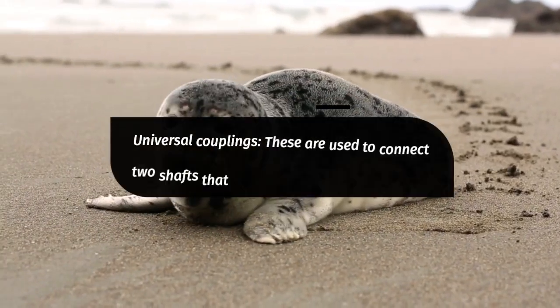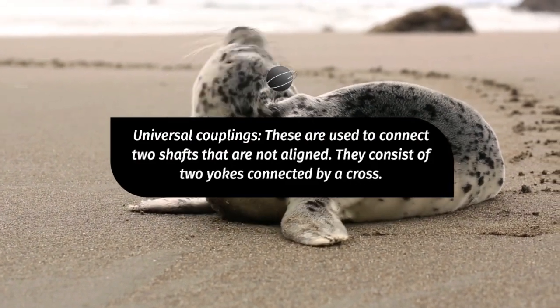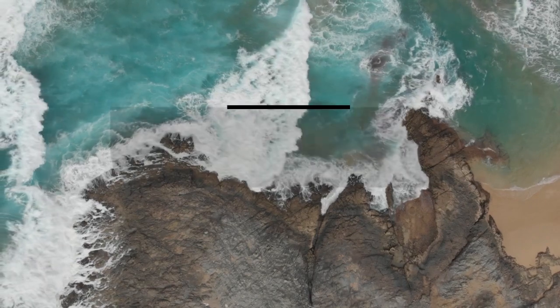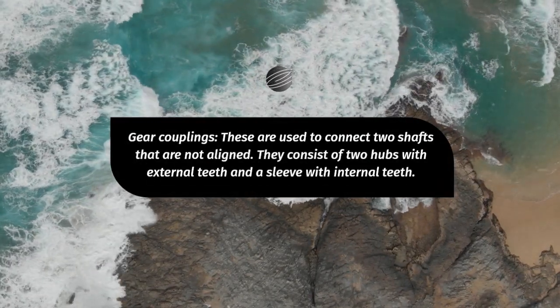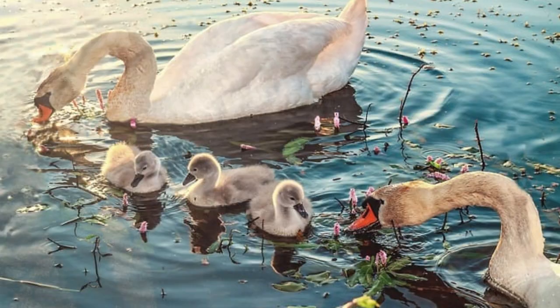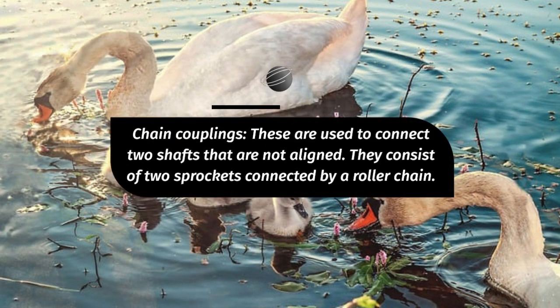Universal couplings are used to connect two shafts that are not aligned. They consist of two yokes connected by a cross. Gear couplings are used to connect two shafts that are not aligned. They consist of two hubs with external teeth and a sleeve with internal teeth. Chain couplings are used to connect two shafts that are not aligned. They consist of two sprockets connected by a roller chain.